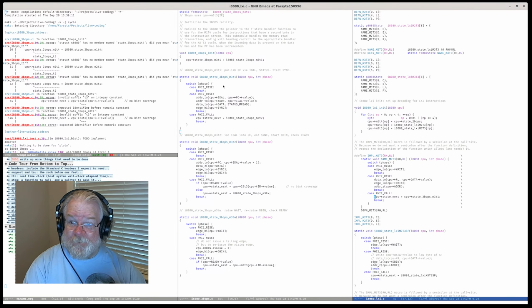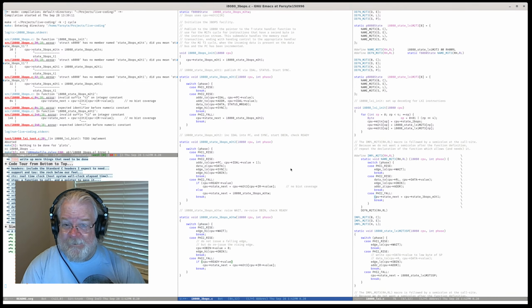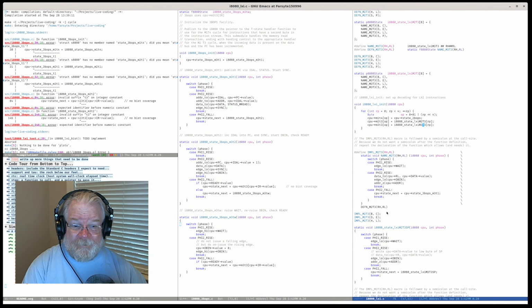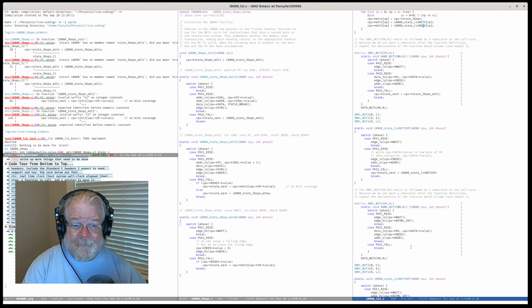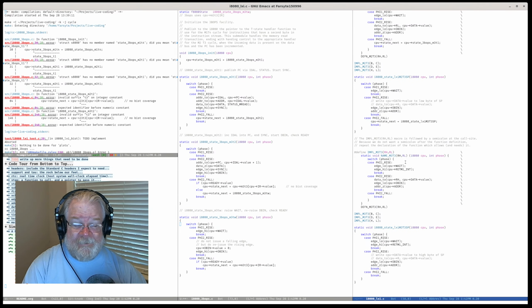Okay, so then we get into the third byte of the operation. PC, IDAL, data, all this is the same, bada bada ba, and we end up going M3T3 here and here. M3T3 gets us back under control here, where again we are doing the high byte of the register pair, and we are declaring the end of the machine cycle under the instruction. So the next T state is going to be the start of an M1T1, and that's good on both of them.